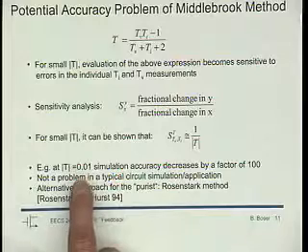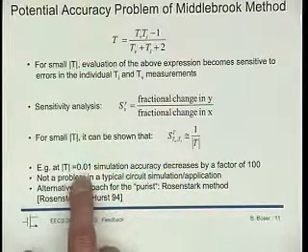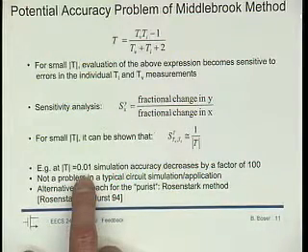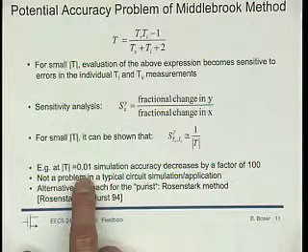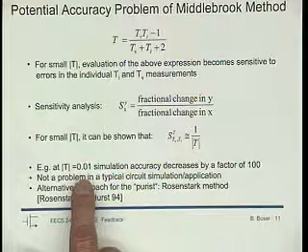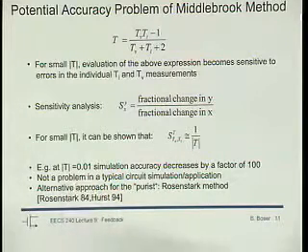Well, 10% isn't a particularly good accuracy for your simulation. But you have two things that go for you there. One, you probably don't care too much once the loop gain has dropped to 1/100. In most cases we don't really need to know exactly what's going on there anymore. And the other thing is, computers are powerful and inexpensive, so you can just tighten reltol a little bit and make up for that factor if you want more.